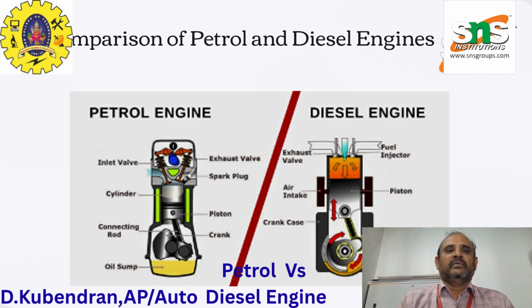The third parameter is air-fuel mixture formation. In a petrol engine, the mixture is formed in a carburetor or fuel injector, because a carburetor is essential in a petrol engine. But in a diesel engine no carburetor is required. Instead, fuel is injected directly into the compressed air, so a fuel injector is required in a diesel engine.